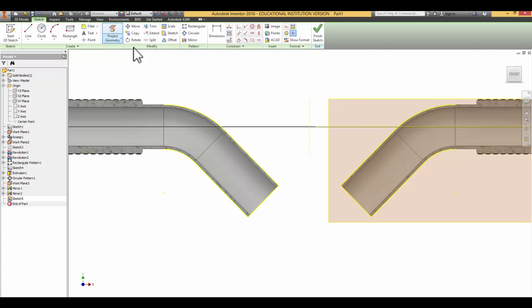So what I'm going to do now is I'm basically going to create an arc that's going to go from here to right here. And I'm just going to pull it down, and I can see I've hit the tangent symbols. So I'm going to stop right there. If you don't get that, then all you need to do is just put it on there. So if you had an arc, in fact, I'll delete that last one. I'll put it back on there and show you how you would do it.